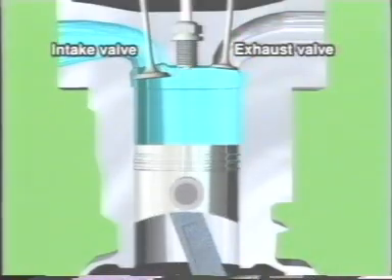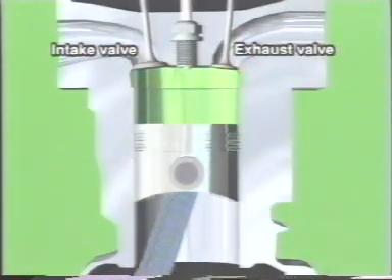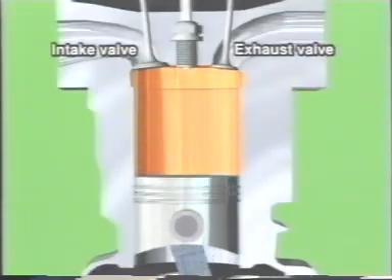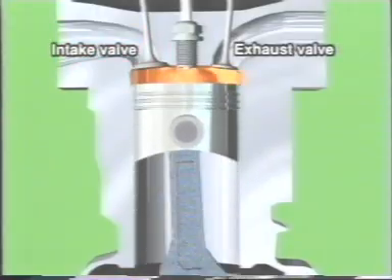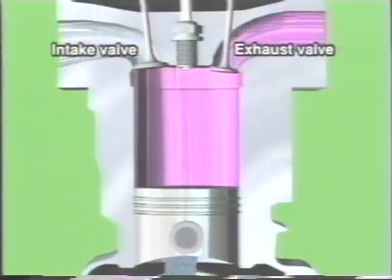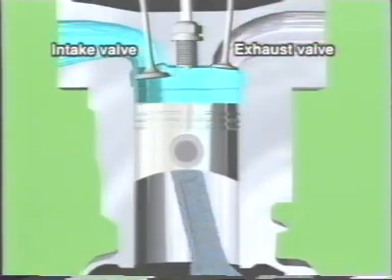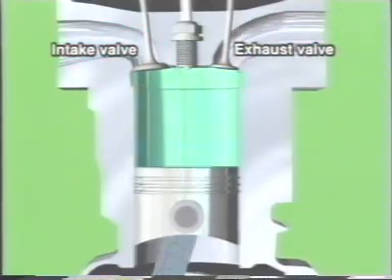Specifically, the intake valve starts to open before the piston begins its intake stroke and closes after the stroke. Similarly, the exhaust valve starts to open before the piston begins its exhaust stroke and closes after the stroke. Such valve operation timing ensures efficient intake and exhaust.